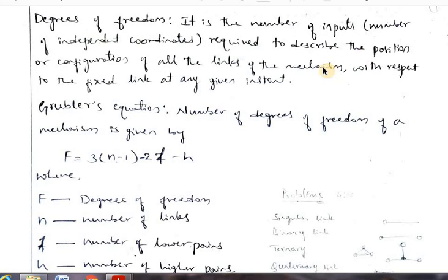For example, when two elements are pulled together, and if one element is able to slide in only the horizontal direction, then we can say it has a single degree of freedom. We have already come across a shaft in a circular hole example, where the shaft can have a rotary motion.